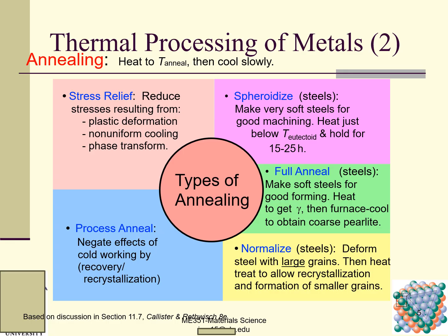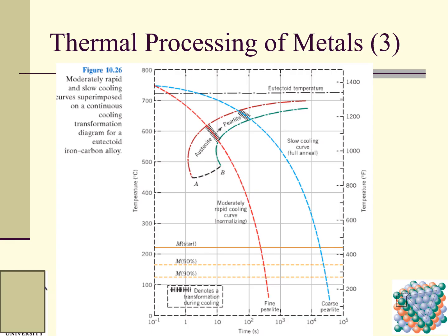If I were you, I would like to know stress relief, spheroidizing, full annealing, normalizing, along with process annealing, and know some basic ideas. If there is a need, I can come back to see this slide. And I know the fundamental principles of annealing: elevate the temperature and stay there, soak and hold for a certain amount of time, and then cool down the specimens. And then we talk about this thermal.